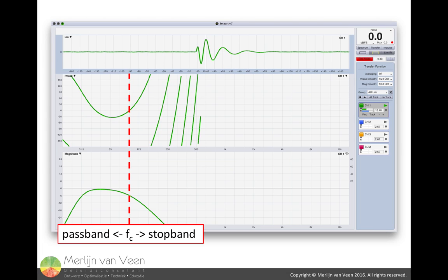If the delay locator locks in, it will typically do so to the highest peak, in what barely resembles an impulse. Typically the passband of the subwoofer. But those aren't the frequencies we're trying to align our main speakers to.